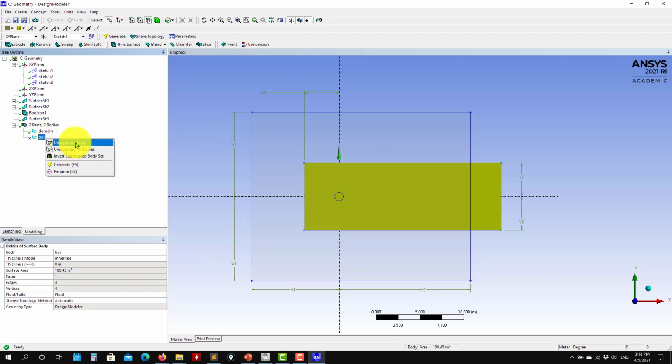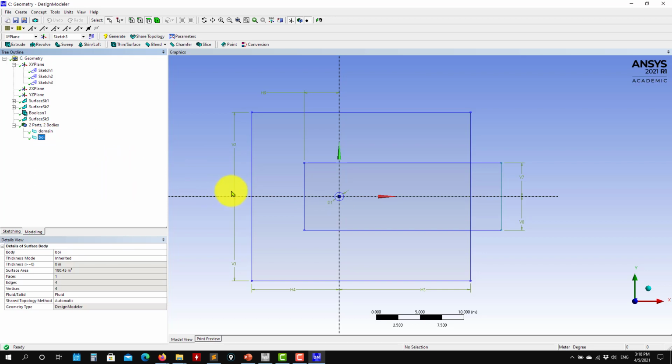Okay, what is going to happen is that you are going to pass these two bodies to the meshing stage, and the meshing is going to generate two different meshes. So that's why you want one single body. Okay, but in this case, the second body, you want to use it to project a finer mesh in the other one. So there is another option available in Ansys Meshing to do that; later we're going to see how to do it. Okay, so this body can be of any shape. I put here a square, you can have multiple bodies. So you just put it here in your tree, and when you go into meshing there, you can say, okay, this extra body that I am importing here will be a body of influence. So this is all for the geometries.